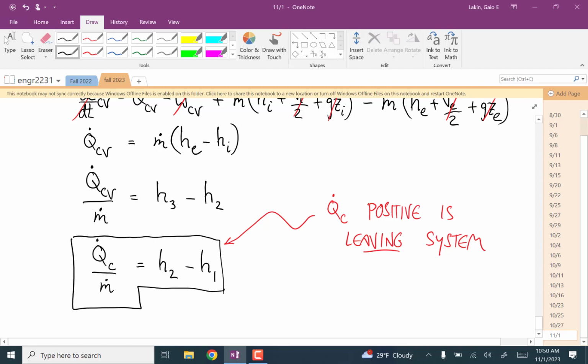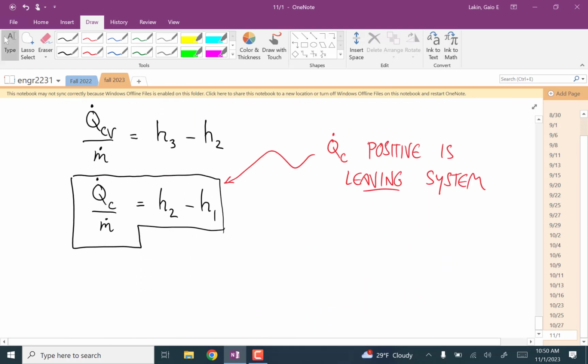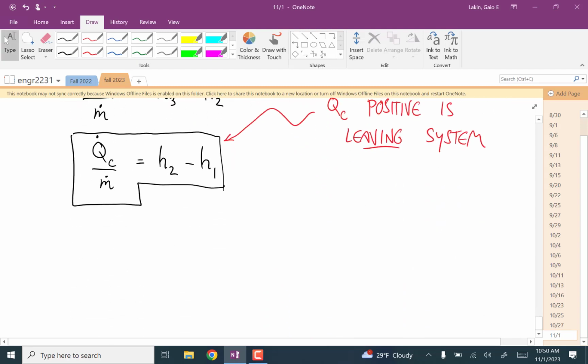We'll talk about some other practical considerations later on. Like one thing is you don't want the temperature and pressure too low coming out of the turbine, because then you get a phase change. And even though mathematically that's not bad for the turbine, having liquid in your turbine is really hard on the equipment. So we'll just continue with this next time, and then we'll get into some problems.